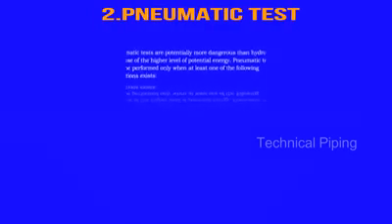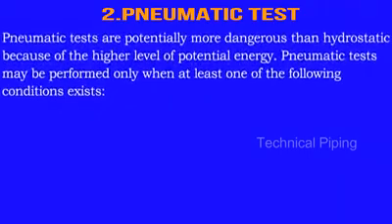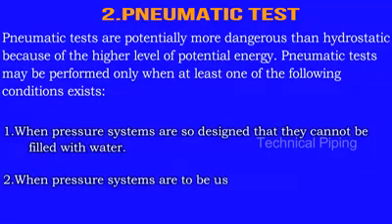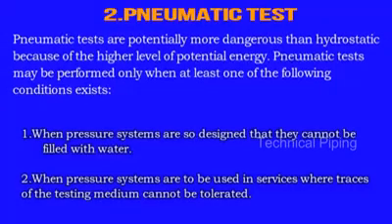Number 2. Pneumatic test. Pneumatic tests are potentially more dangerous than hydrostatic because of the higher level of potential energy. Pneumatic tests may be performed only when at least one of the following conditions exists. Number 1. When pressure systems are so designed that they cannot be filled with water. And Number 2. When pressure systems are to be used in services where traces of the testing medium cannot be